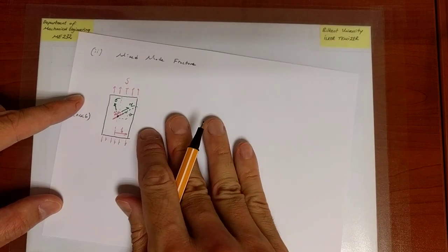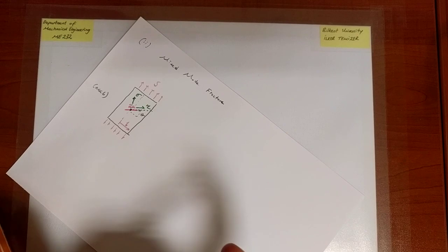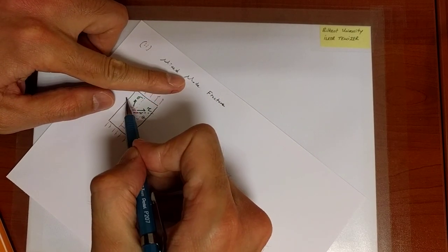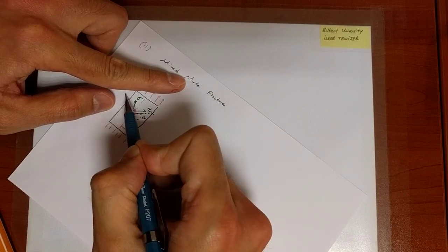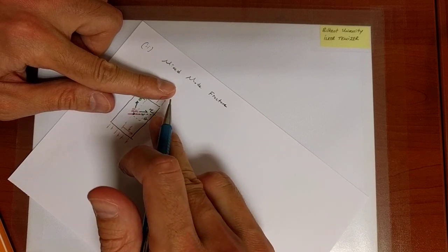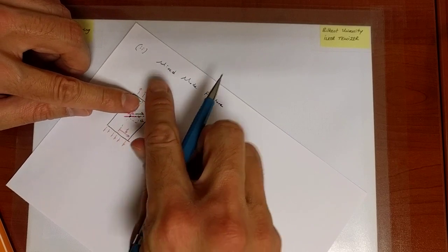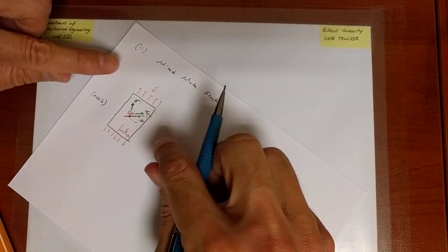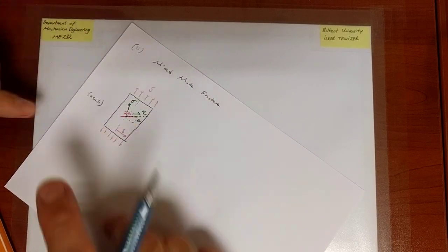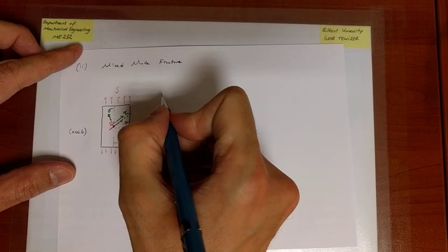Now, when I then rotate the picture locally, if I just concentrate on the normal stress, I will see a crack that is loaded in the normal direction. It's a plate with a through-thickness crack. It's our prototypical scenario. And if I concentrate only on tau, I have a plate, but it is loaded in shear. Now, the tension case I've seen before. Shear, I haven't, but I know that it's a mode that I can consider. So first, let's take the case of mode 1.